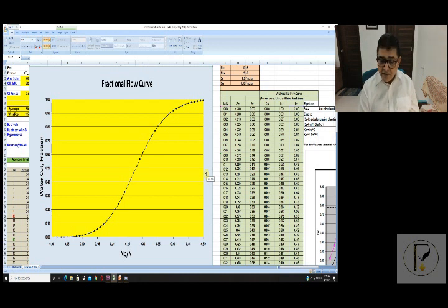So at this instant, the fractional flow curve has shifted to the right. That means water cut is depressed in the reservoir. That's yielding higher recovery. Now you are getting around 37% recovery at around 90%. Okay, so you can see now the benefits, how fractional flow is linked to this mobility contrast.